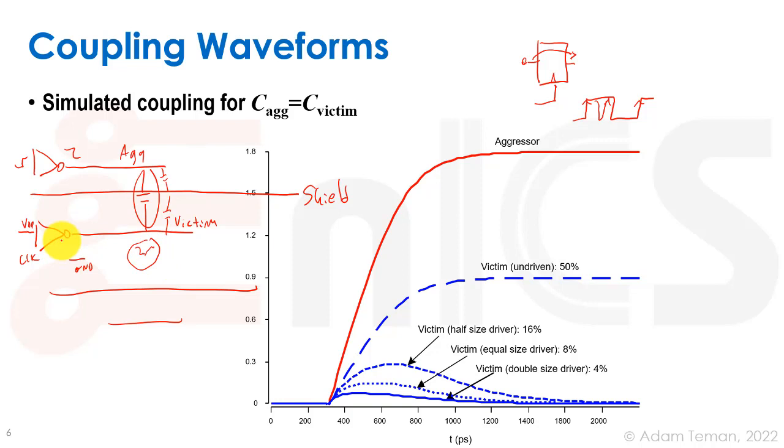On the other hand, as you can see here, this shield is a net that's going to be close to the clock net, and therefore adds capacitance. So it for sure doesn't reduce capacitance. In fact, to reduce this effect of the coupling capacitance, which causes us to have speed and power issues, RC issues, what we're often going to do is put double spacing. So this is going to be a higher space between the clock net and the shield that is around it.